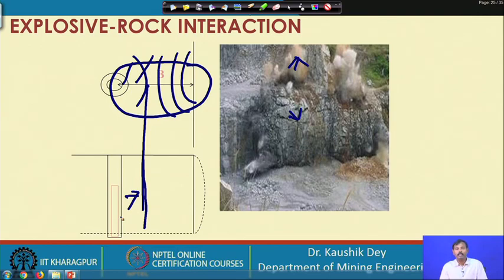So, basically this is the utilization of the time gap between the shock energy release and the gas energy release. By understanding the energy transferred from the explosive to the rock from the crater blasting experimentation, we are able to design a proper burden for our rock fragmentation.